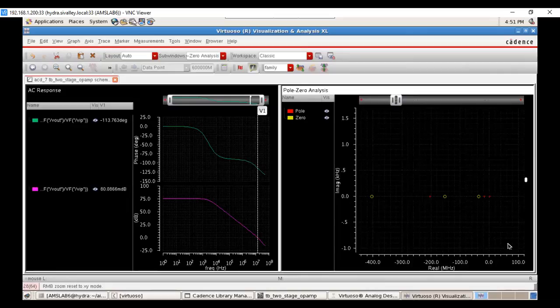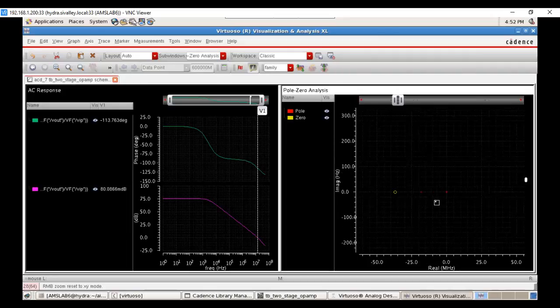Yeah, so I think there are two dominating zeros which are causing issues inside my frequency response. This zero will be cancelled out by this pole effect. Though they look apart here in the graph, if you see the frequency, they are very close by. You can see that in your simulations also. The frequency of this pole and this zero will be very close, maybe 1-2 megahertz difference. So that's fine. Similarly, this particular zero effect is cancelled by this particular pole.